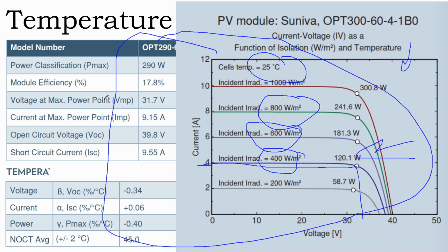And so what that means is when you get into National Electric Code and you start to put these design numbers into your design work, code is going to require additional safety factors beyond what is normal for common electrical design, in order to say, look, the voltage and the amperage that you're designing with on the spec sheet is way off compared to what it will do in the field. And so unless you're making engineering calculations, you're going to have to apply additional safety factors, because ultimately when you're designing with code rather than with a calculation, it's a series of safety factors to get to your safe design.